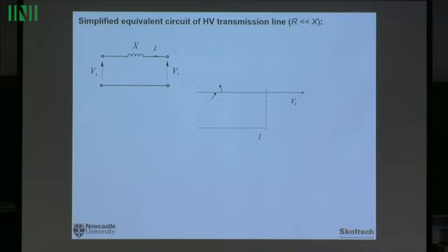Everything here are phasors. It means they rotate at 50 Hertz. They can be frozen at any time, so the reference angle is 0. Let's freeze it so that the voltage VR is at 0 angle, the reference. So this is the voltage VR at angle 0. And then let's assume a certain position of the current I. Typically, those circuits are inductive. That means that we assume a certain lagging power factor, and let's assume that the position of the current I with respect to the voltage VR is like that. Everything rotates anti-clockwise, so the current is lagging the voltage, which is an inductive circuit.